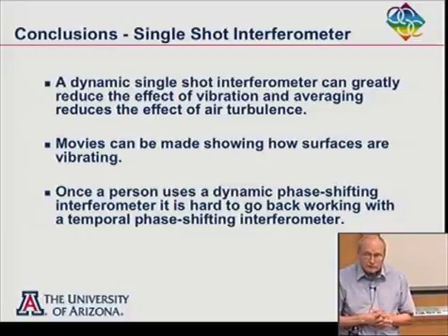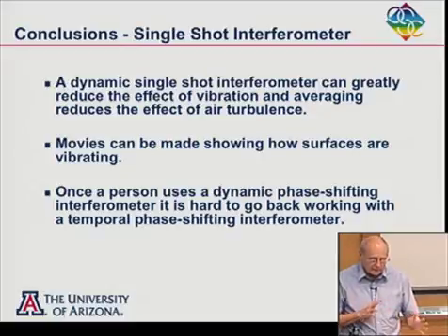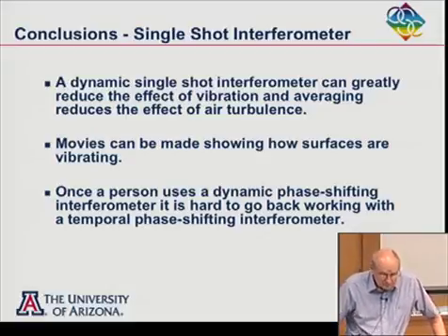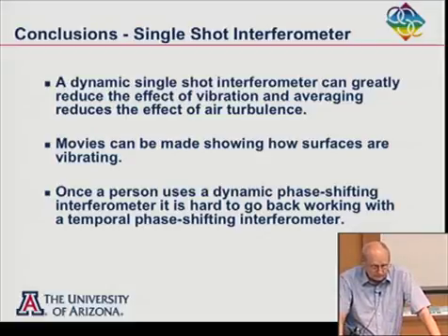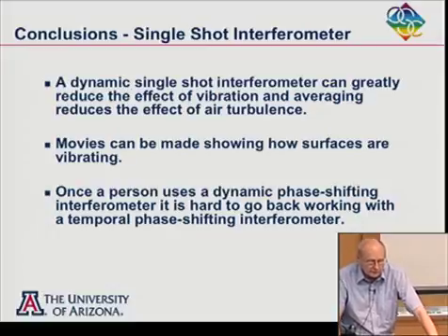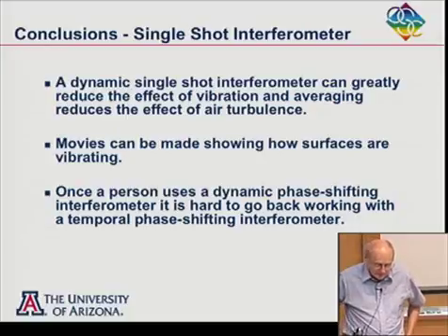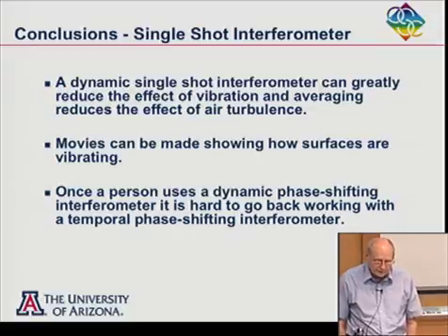So we've looked at several different ways of getting around the effects of vibration. And I really think that these single shot approaches are the best. Some people like it where you put in a lot of tilt fringes and you do a Fourier transform to get the wavefront. Some people like the spatial fringe technique where you put in tilt to get 90 degrees difference between adjacent pixels.